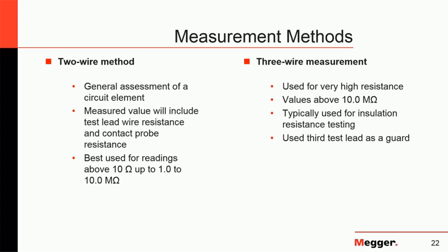Sure. Can you explain a little bit more about why you have to demagnetize the transformer after testing winding resistance? Oh, okay, that's a good question. Like I said, if we do the winding resistance on the transformer, we know that we do that with DC current, so that will magnetize the core of the transformer.